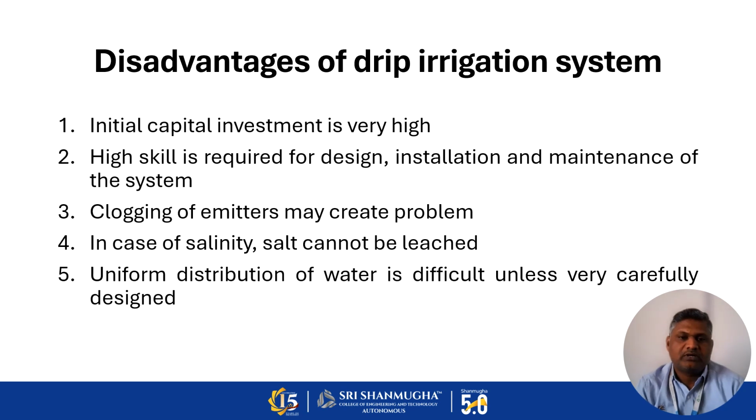Take the example of vegetable crops. Installing drip irrigation for 1 acre will cost around 75,000 to 1 lakh. But in the case of fruit crops like mango, coconut, amla, or pomegranate, the spacing between the crops is very high, so the lateral requirement is very less, and the 1 acre installation cost may vary about 30 to 35,000 only. So this is the capital cost.